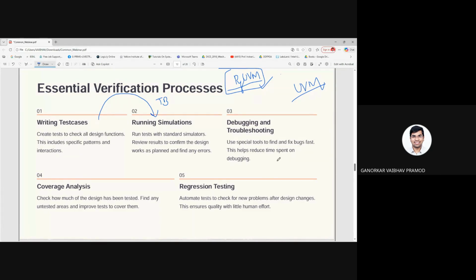Let's consider this is your design. Why do we do regression testing, I'm saying. The RTL guy has updated some code, and you have verified your test cases with the previous code. Then he changes his logic. Because of that, it throws an error, and you haven't run your test cases on the latest design. So the industry practice we recommend is to automate it, so that on every design change, we run all the test cases. That's the basic one.